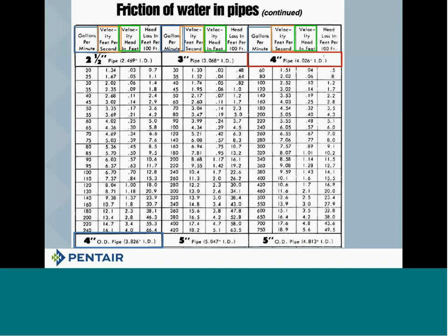But basically, velocity head says we're going to take that flow rate, or that velocity moving through there, and convert it into an energy form that we can use. And, of course, in pump language, the energy form that we talk about is head. All right? And then the last column there is the amount of friction loss in each one of those pipe sizes at different flow rates.